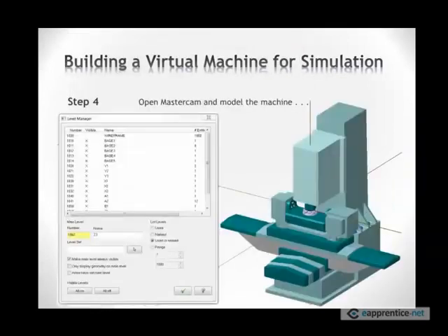Next thing is you actually have to model this up. Now you may be getting models from outside, maybe from the manufacturer, and they may be in different locations. Maybe every model is scattered all over, or maybe in a different view. So you have to make sure it's sitting in a Mastercam World 0. The F9 position is coinciding with your machine's rotary center point, and you model around that. How much detail you want, that's up to you.